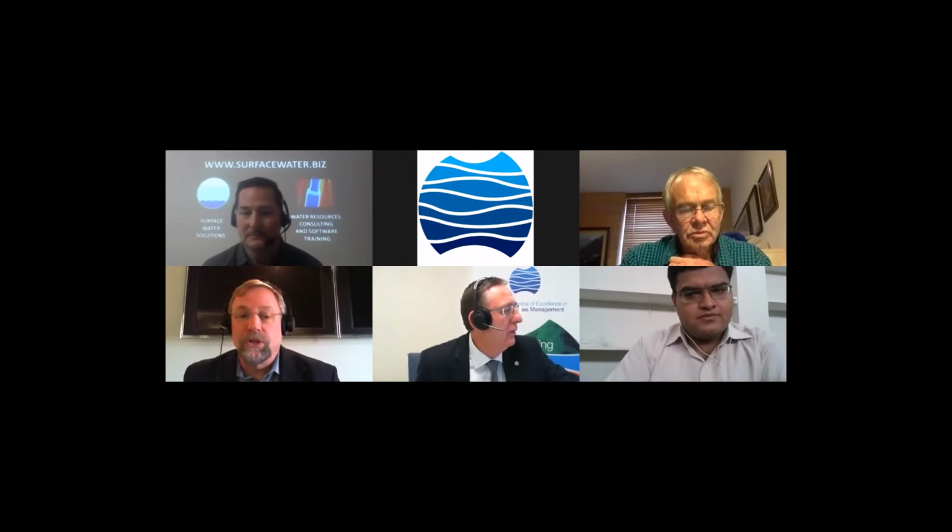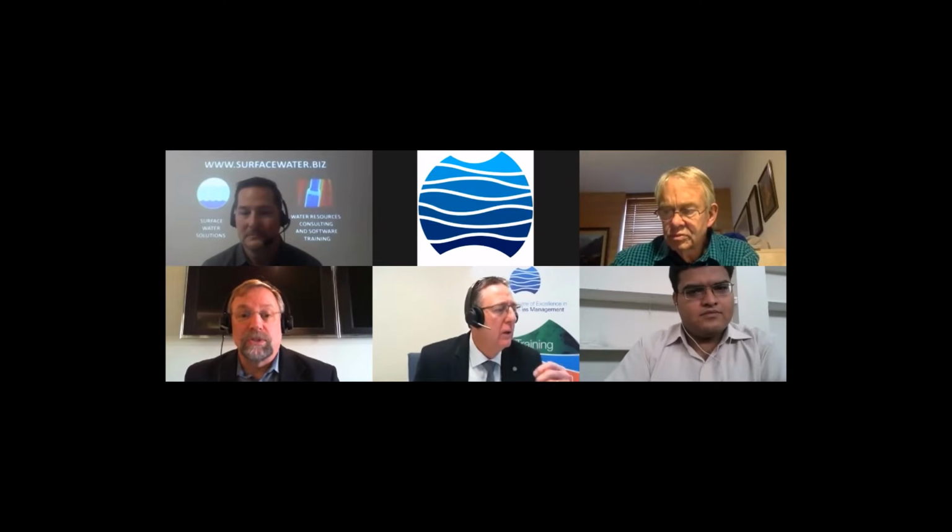All available data that you're going to use for a 1D model would also be used in a 2D model. You can query your results at that gauge location directly within the RAS Mapper tool to also match it to the gauge data, depending on what you have available. If it's just time stage information or maybe velocity as well from direct measurements, you can query your data and your model to validate whether or not your model is replicating that observed data.